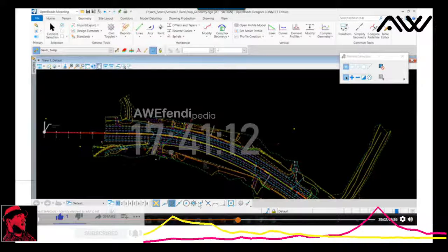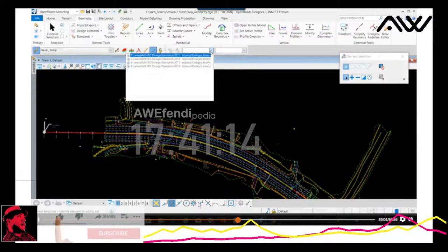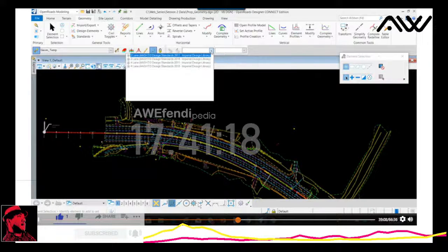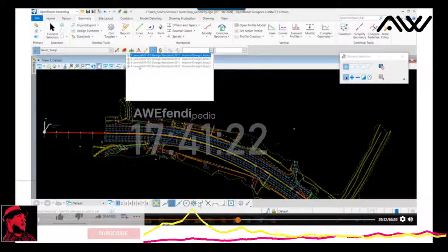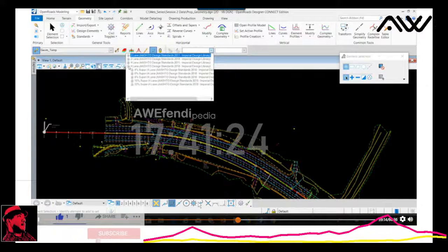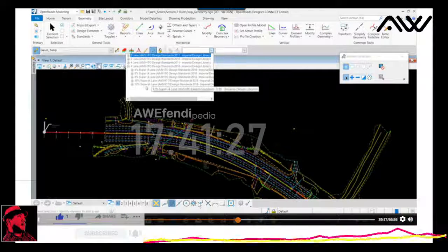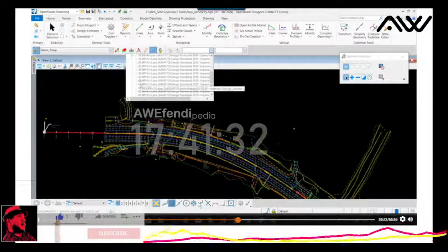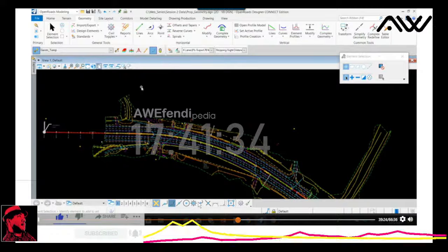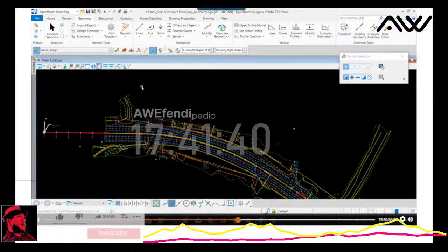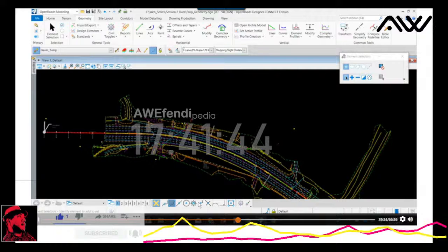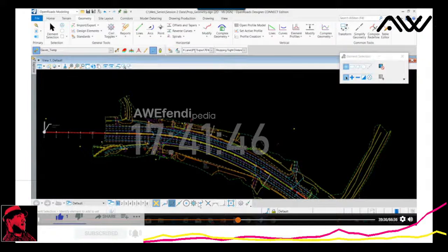Using that toolbar, we're going to be able to select the design speed that we want to use for a particular alignment. In our case, we're going to use a 4-lane based off of 2018 standards. We know we're going to end up somewhere in an 8% maximum for our super, and we're going to use 70 miles per hour, which is the current design speed. It's posted at 65 for our horizontal alignment. This is based off of the AASHTO standards for 2018, 70 miles per hour. Now, I have 2 buttons here. We're going to use this particular button.